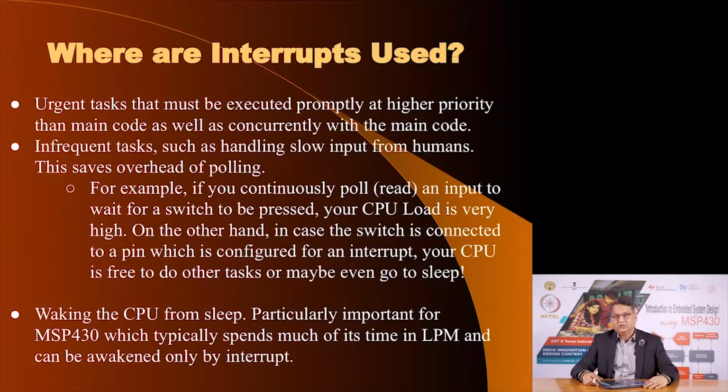Infrequent tasks which happen once in a while, you would like to deal with them using an interrupt, and as I mentioned, human inputs are very slow. They may be infrequent compared to the rate at which a microcontroller can execute a program. Human interaction is much less frequent, and so you could handle the external events generated by inputs by humans through interrupts.